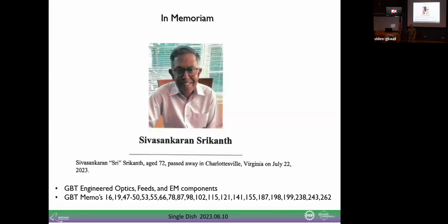But since the first amplifier sets the noise temperature, you want it as low as possible, and that's the reason to cool it. If you don't cool it, your noise temperature is just going to be higher because your first amplifier has a higher noise temperature. It's the same concept. Your other components really aren't affected as much.